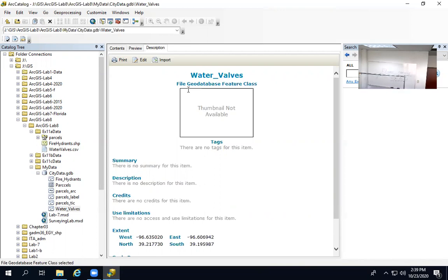Now, these guys here who work in the project want to draw some bus lines. So, where will we draw them? We need to create a brand new layer where we will start drawing our bus lines. So this is the next step here. Create from scratch a new feature class in the city data geodatabase. Let's call it water lines. What type of feature class do you think the lines should be? Answer this question in your Word file.